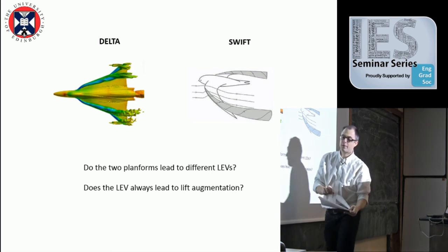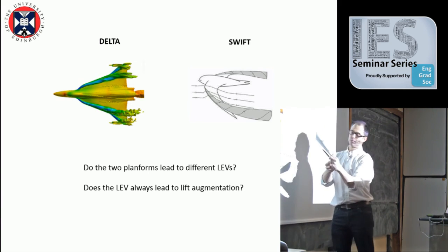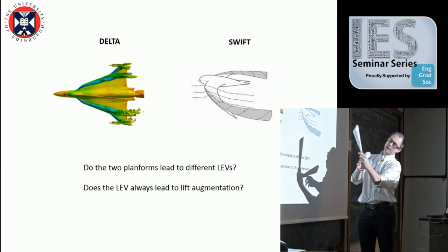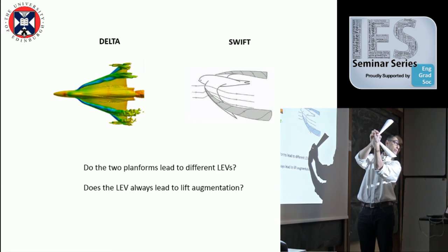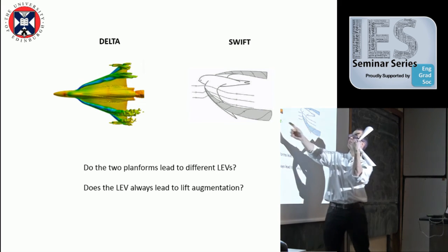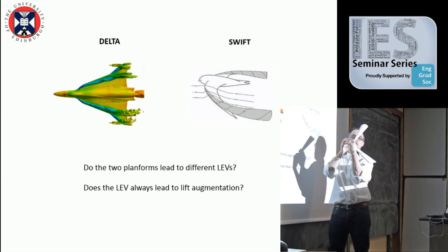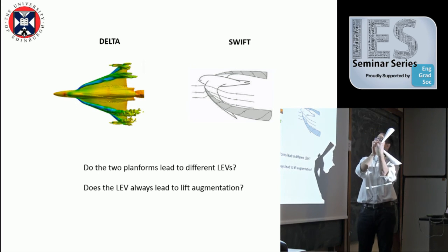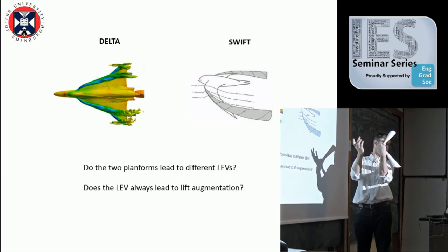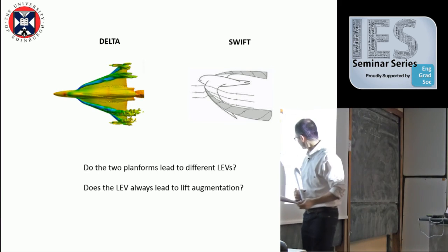Now the question is, when you look from the top, this vortex is actually sustained by this wall. If I now put this vortex on this geometry, initially the vortex is smaller than the wing, but there will be a point where the vortex becomes larger than the wing, because the vortex is always increasing in size, because it's capturing more and more flow the more towards the trailing edge you're moving. So the vortex must increase in size. If the wing is actually decreasing in size, there will be a point where the vortex doesn't have the wing below it.